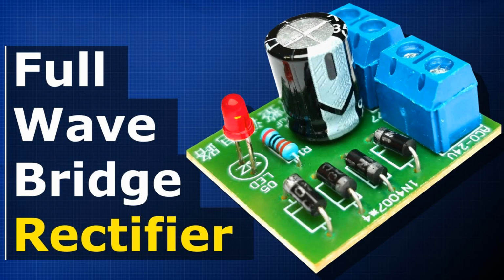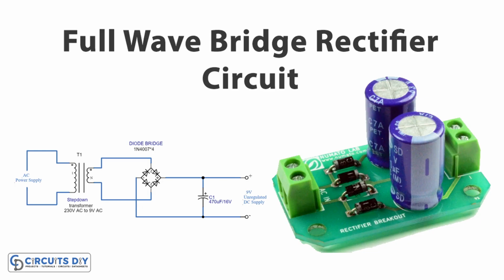Isolation. Depending on the design of the power supply, isolation may be provided between the input, AC mains, and output, DC load, circuits to improve safety and prevent electrical hazards. Isolation transformers or opto-isolators may be employed for this purpose. Output protection. Power supply circuits often include protection mechanisms such as overvoltage protection, overcurrent protection, and short-circuit protection to safeguard both the power supply and the connected load from damage due to electrical faults or fluctuations. Overall, bridge rectifiers play a crucial role in power supply circuits by converting AC power from the mains into stable and reliable DC power for a wide range of electronic devices and equipment.